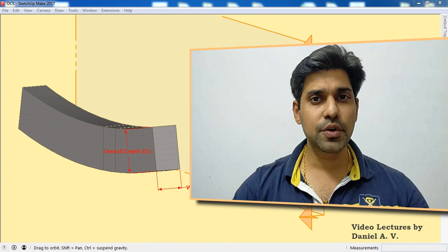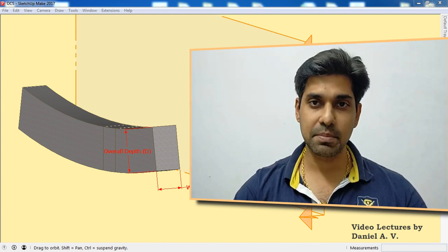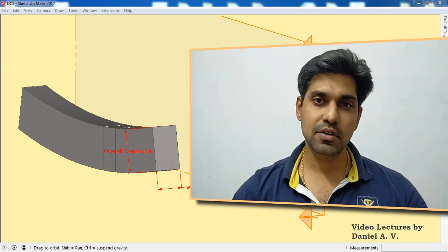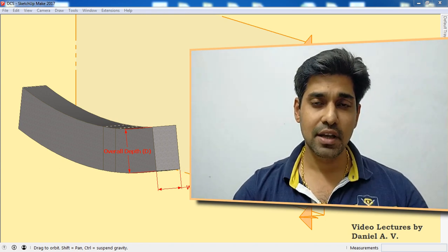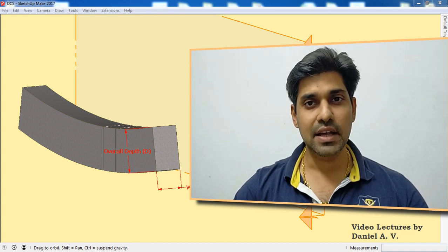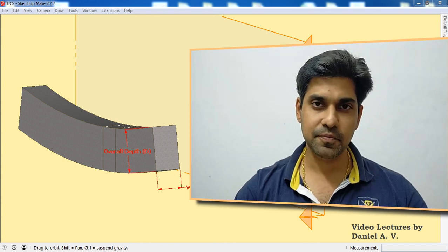Here we are going to discuss in detail the derivation of moment carrying capacity of a singly reinforced beam, the assessment of neutral axis depth, and also the very basic assumptions that we make as engineers to simplify complicated calculations.